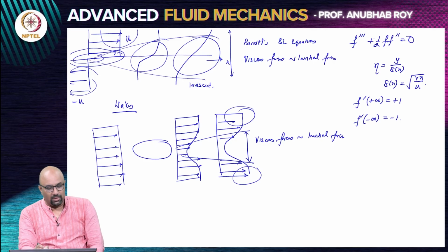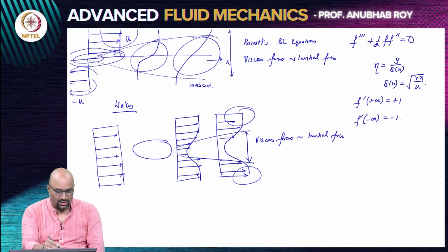So even in problems of flow past an object, when you are trying to understand a wake, when you have moved sufficiently far downstream, you can again describe the wake where it evolves in a self-similar manner, and the governing equation of how the wake is modeled can be done in the same manner. You have two streams, or there was a uniform stream that was retarded by this object. So it has to satisfy the no slip boundary condition on the object.